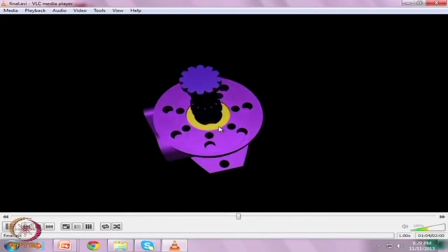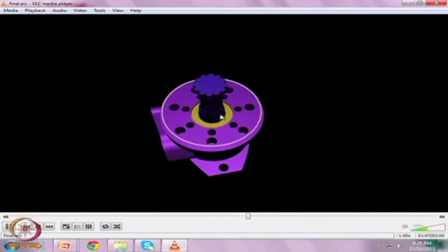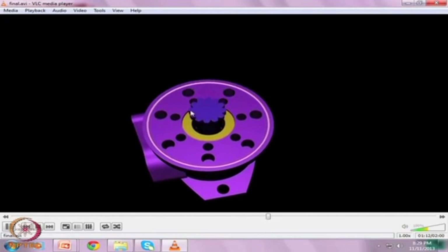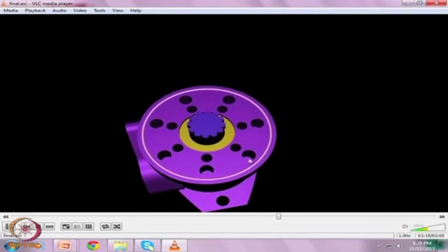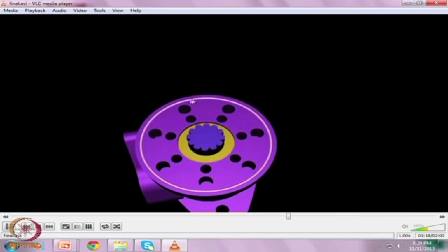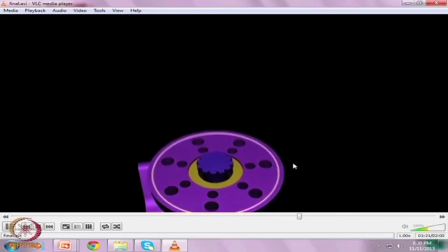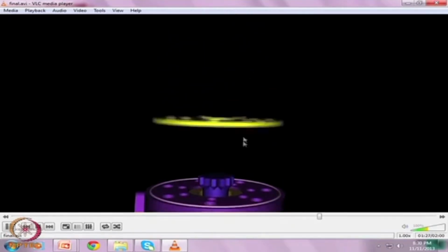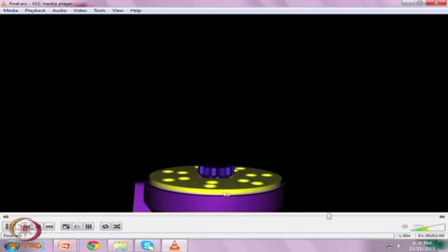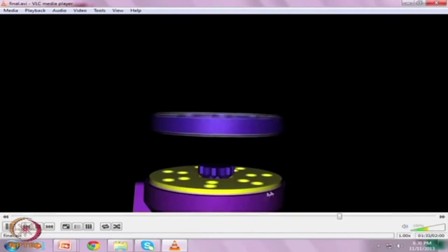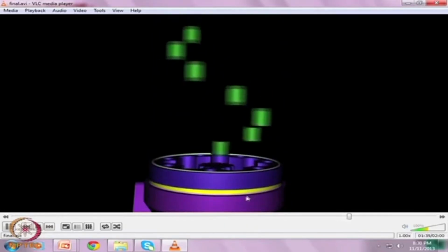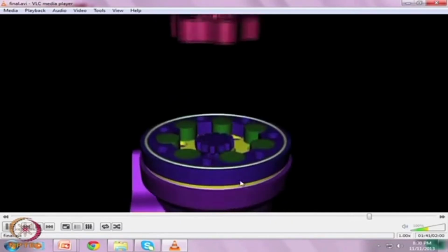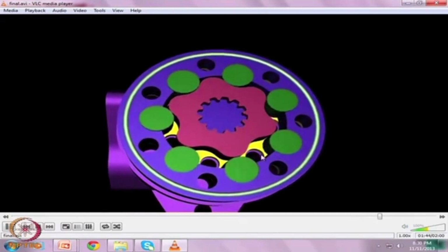Inside of this shaft there is a gear coupling. So, this is being engaged to this gear coupling, and this portion will be engaged to the star gear, and this is a groove where the oil seal is put to make it leak proof. Then you will find that this plate is called the valve plate. This plate is required because the star is rotating, so rubbing against the main body is not suitable. So, we need a valve plate which we can replace easily also.